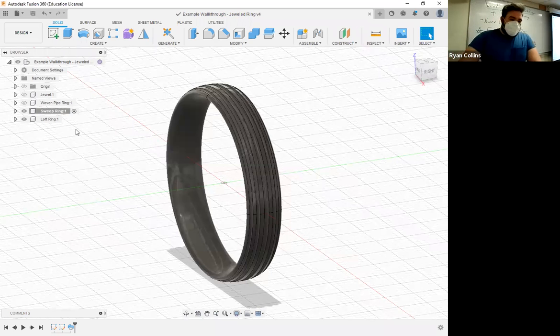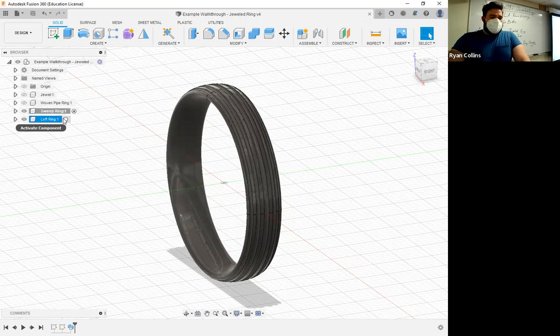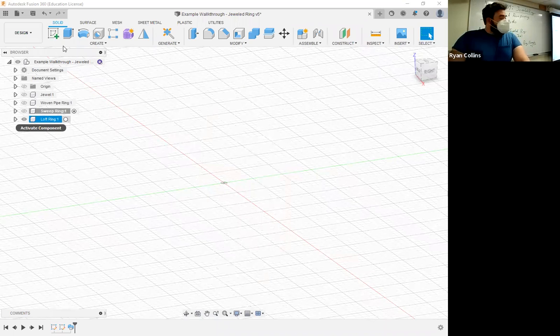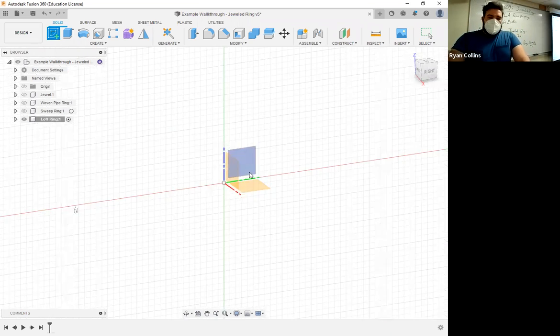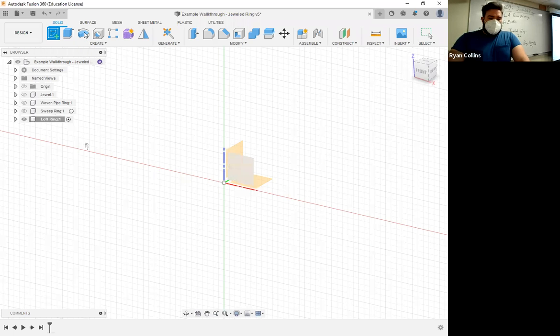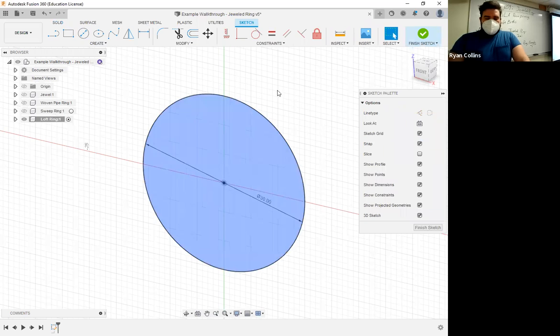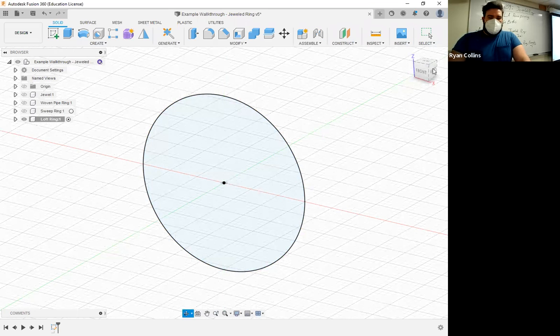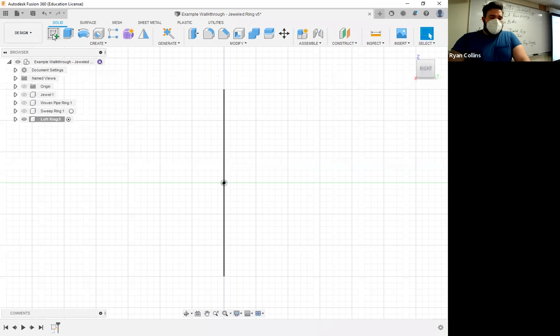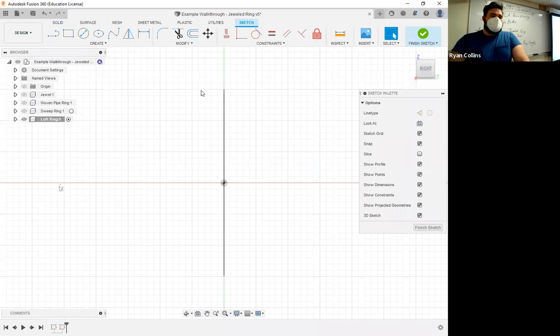All right. So last selection, let's go to Loft. So basically the same set of steps here. Select the front profile, make a circle. We'll go to 30 again. And finish sketch. Now I'm going to go perpendicular to that, and I need 2 sketches here.